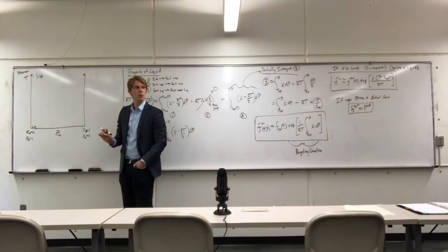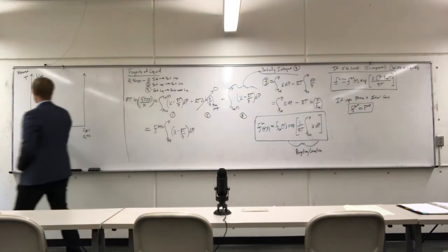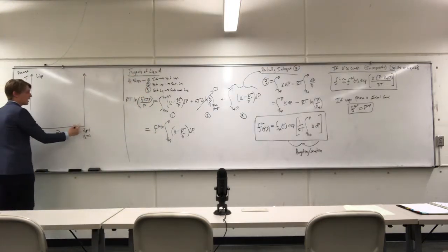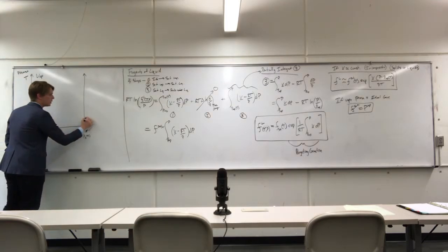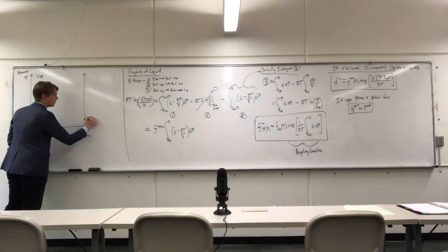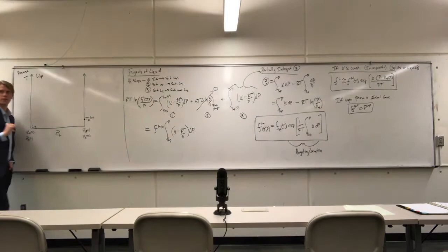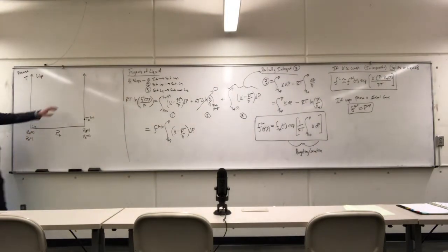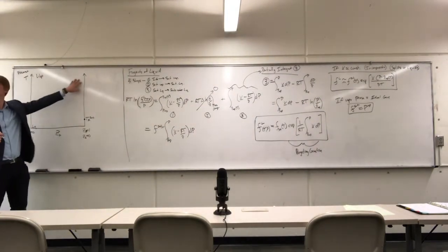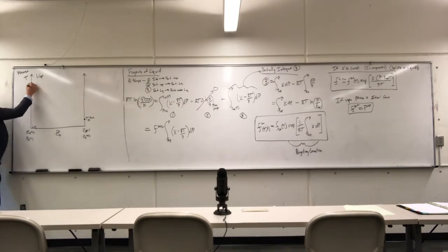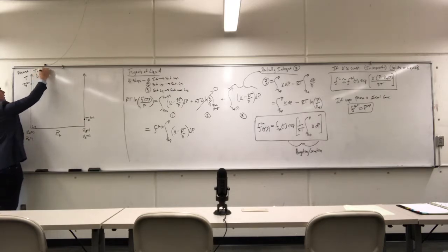Lower. So I should draw the saturation temperature for pure fluid A down here, meaning it's got more of this space up here where it's a pure vapor. Then for fluid B, it's going to be up here, and this is a TXY diagram.